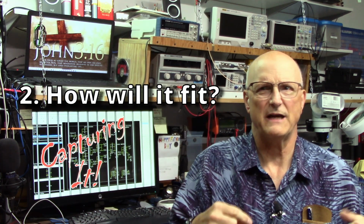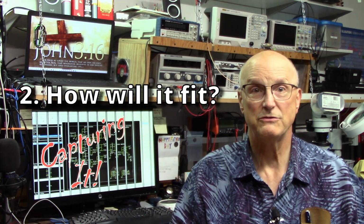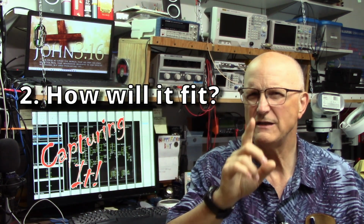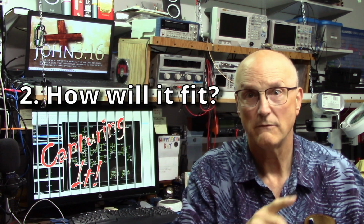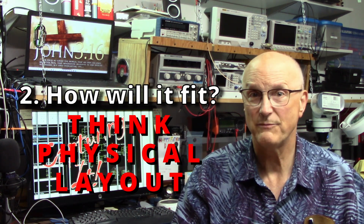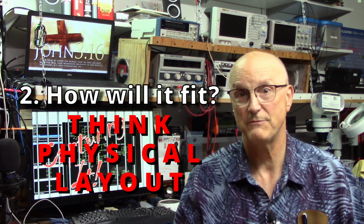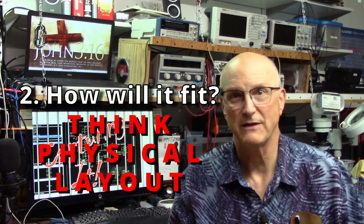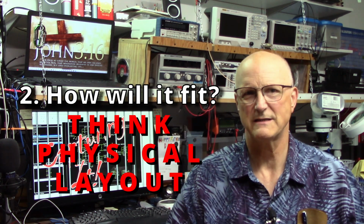Now, we talk about our design here, which has 2 op-amps for each of the channel input amplifiers. We chose to use a chip that has 4 op-amps in the package. So, which 2 of these 4 are we going to use for each channel input amplifier, and in what order? Think physical layout. If you don't, you will get into PCB layout and have to double back and think about it anyway, moving things around to make PCB layout sane or even possible. Now, chances are you'll still have to do some of this, but here in this process, as we make the schematic, we can try to minimize some of that.